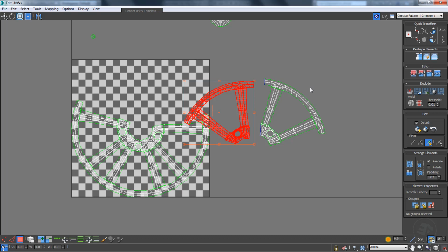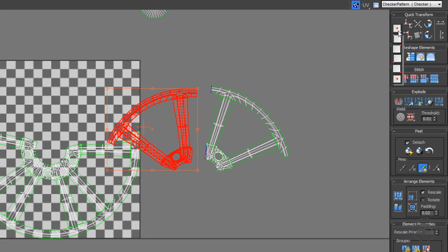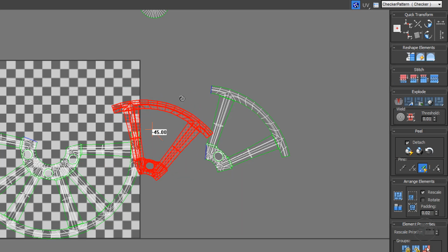There is no option in the editor to input the angle of rotation. This is not the only diminution of function. Notice after breaking the UVs, the origin, or the central pivot, of the original projected UVs is not inherited by the broken ones. And there is no option to align the UV's pivot to the center of the map.